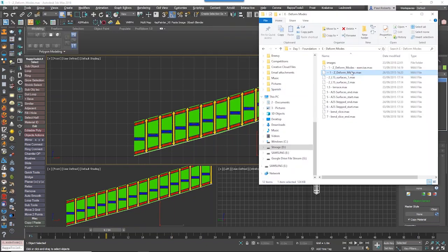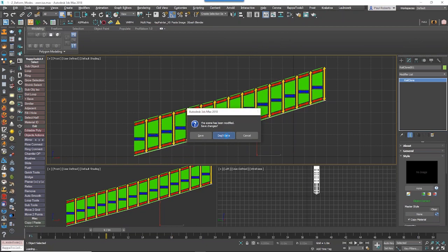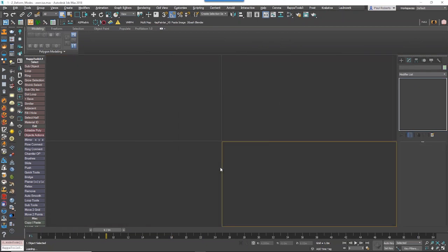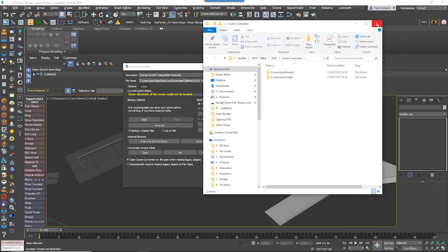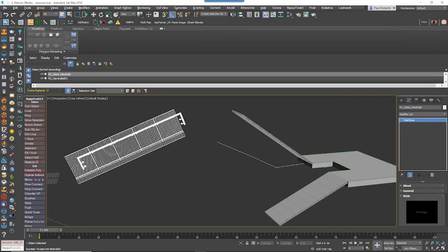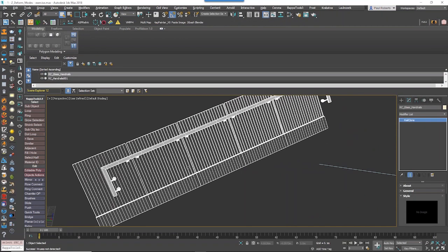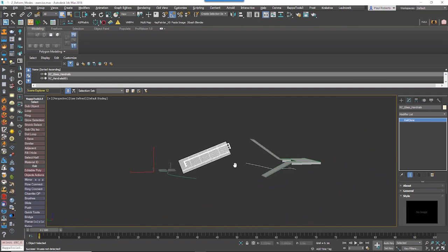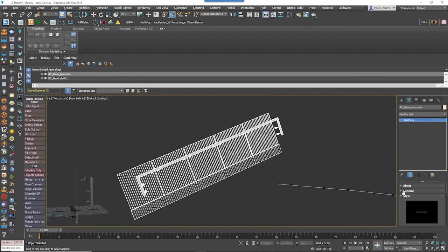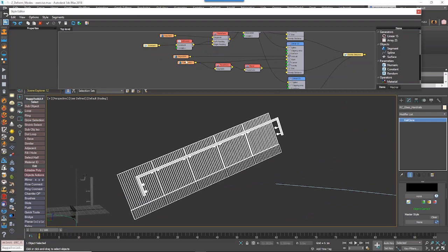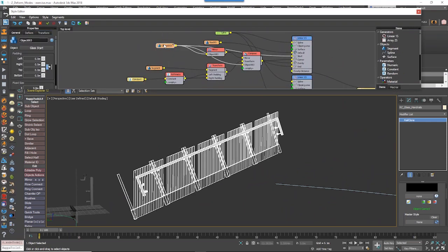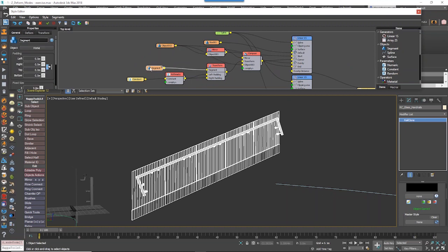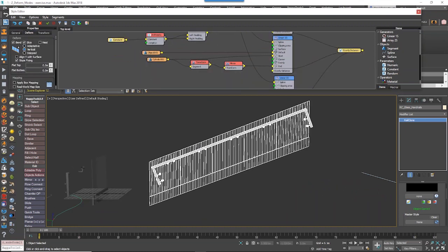So looking at a real world example of that, we have a railing here. At the moment, it's in adaptive mode, so it's coming out sort of perpendicular to this spline, but we want to change it. So we can easily come in and just change these segments. All I need to do is change these to vertical, like so.